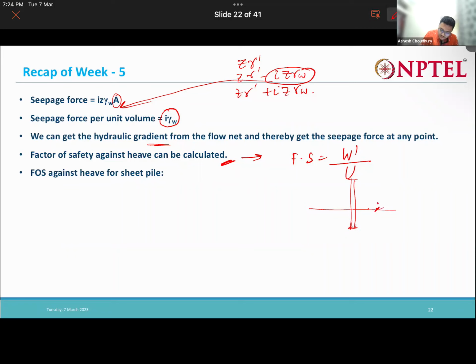See, at this point you have lost your critical hydraulic gradient. Okay, so the soil comes out here. Then again the soil from below will also get eroded, so a pipe-like channel is formed. Water continuously comes out from here, flowing and pushing the soil. That is called boiling, because if you see from the top, you can see some bubbles on the soil.